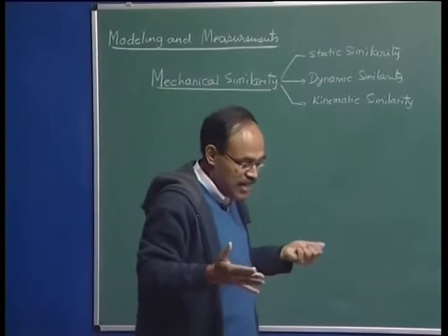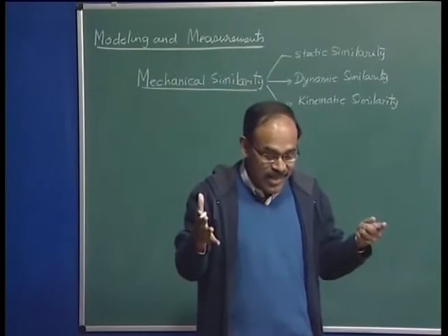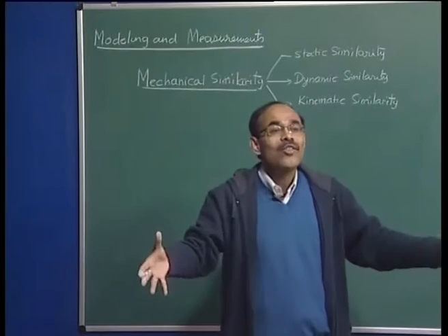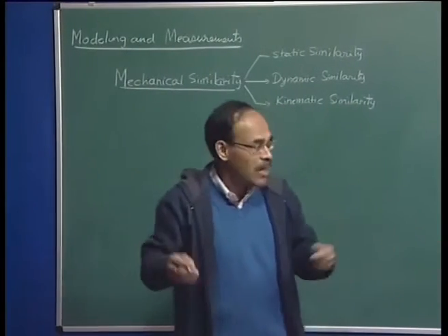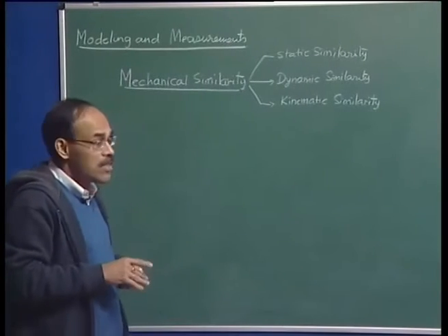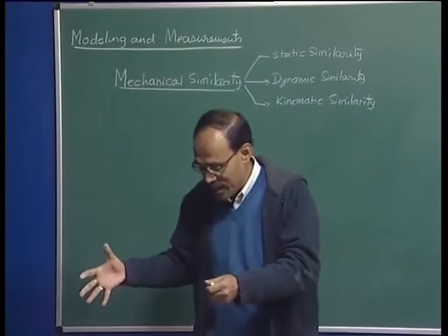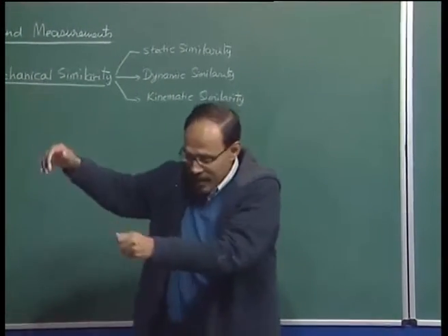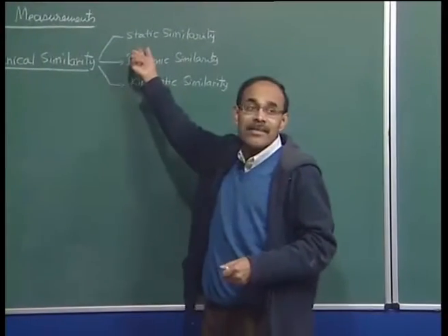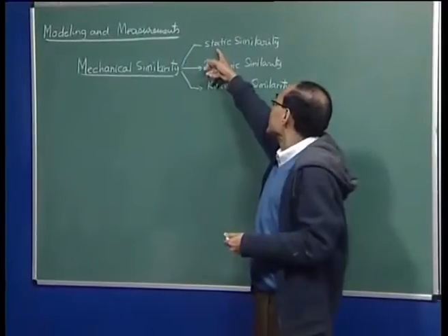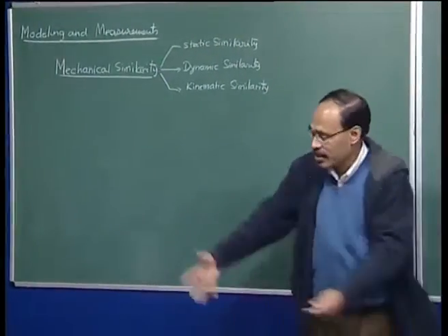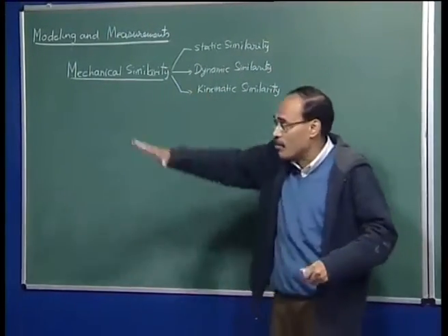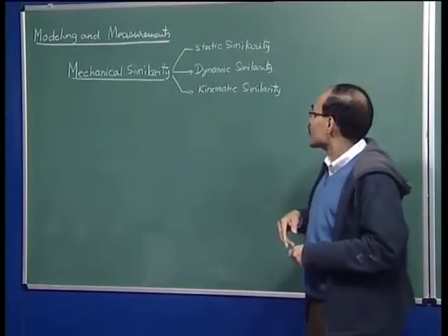For example, we would require static similarity analysis in order to predict the force which will be acting on the wall of a steel making reactor, ladle, tundish, or a basic oxygen furnace. Similarly, if you have a holding ladle and we would like to pull that ladle and find out how much the free surface will oscillate as a result of this pulling. So from rest we want to accelerate the vessel and then lift the entire mass, which is sitting on a cart or a train. The forces necessary and their consequence on the meniscus oscillation can be addressed through static similarity.